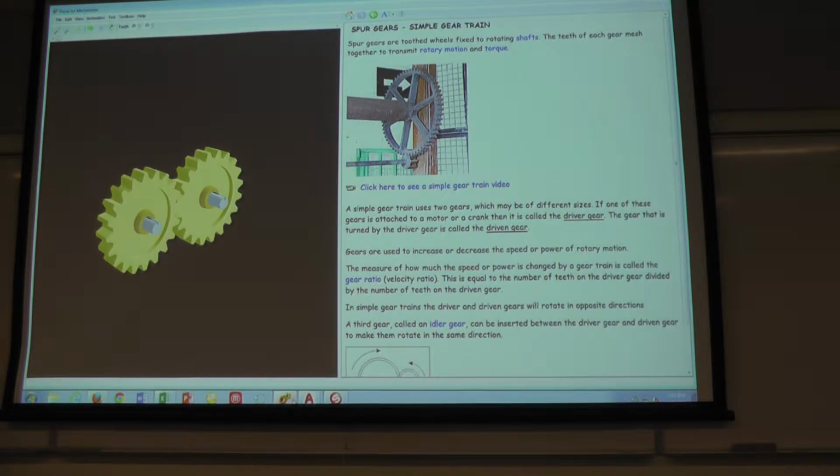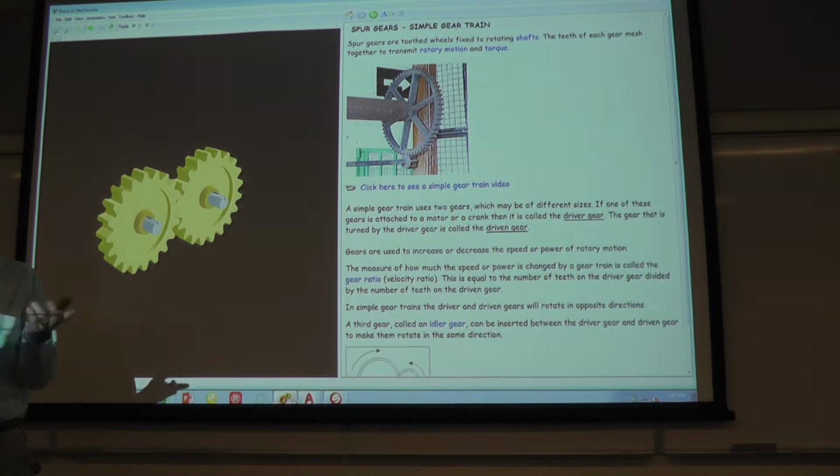All right. So I've got my little mechanisms DVD that's kind of interesting. We've progressed from flat belts and V-belts, which transmit power from a motor to some kind of a device. They're good for certain circumstances. They're not so good in other circumstances. Wet environments are one where they tend to slip. The belt stretches, and if you can't adjust it, you get some slippage and some squeaking and things like that.